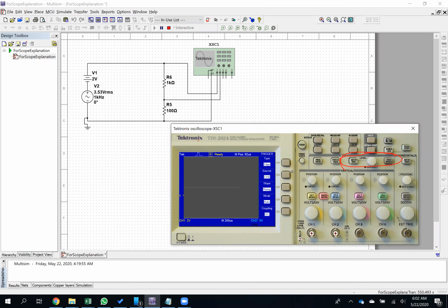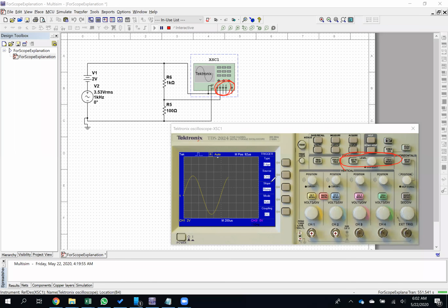Now this scope's not jumping if I put it to channel 2, but normally if I were to put the source to channel 2 with nothing connected, oh wait, yeah, I do have channel 2 connected. Okay, so let me put it to channel 3. Notice that because I have nothing connected here on channel 3, with the trigger source being channel 3, the channel 1 waveform's jumping all over the place, right?